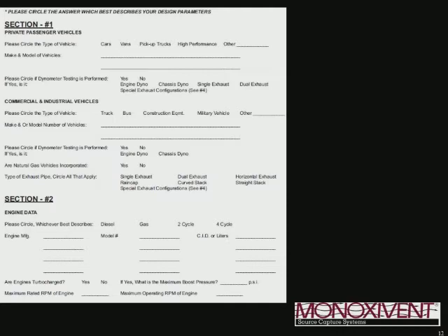Are they natural gas? Is there a turbo? Basically, the most important, I mean, all of it should be filled up, but most important is the engine data, the cubic inch of displacement or liter, and the RPM. How is it going to be run in a particular application?